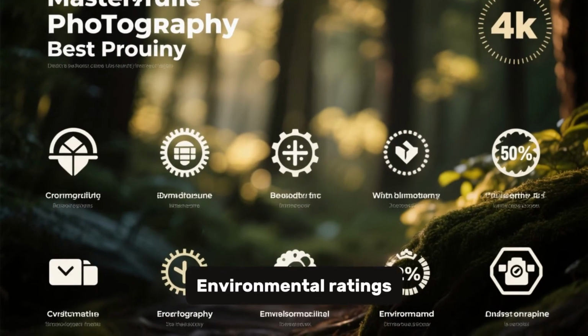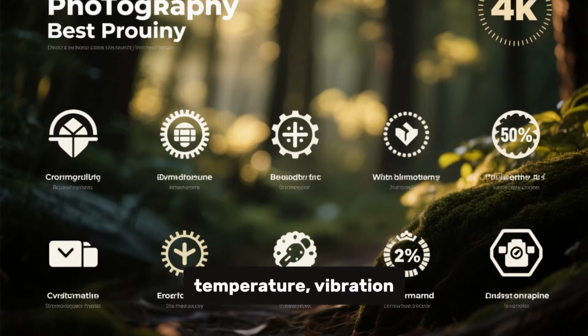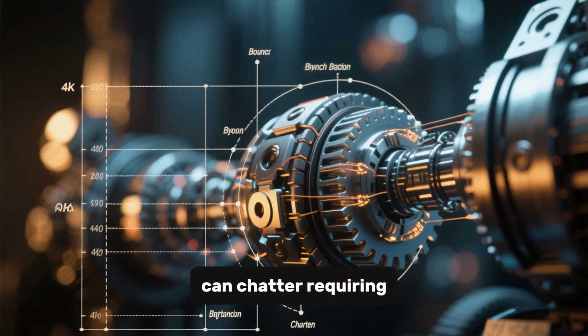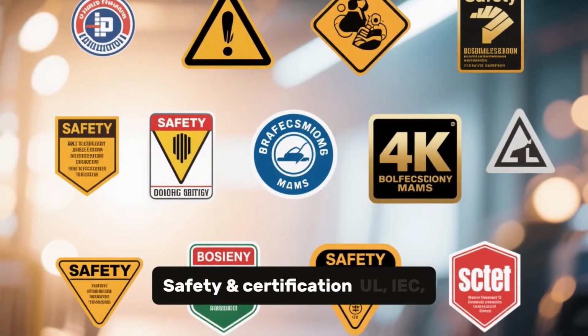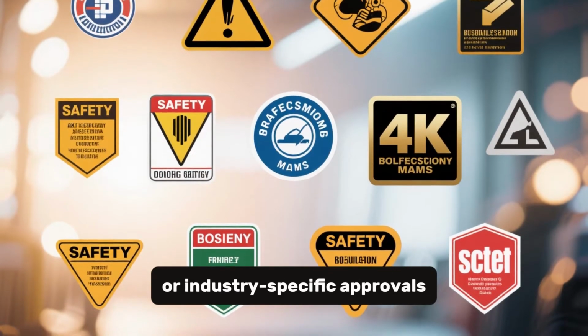Environmental ratings, IP protection against dust/water, temperature, vibration. Bounce behavior: mechanical contacts can chatter, requiring debouncing in digital systems. Safety and certification: UL, IEC, CE, or industry-specific approvals.